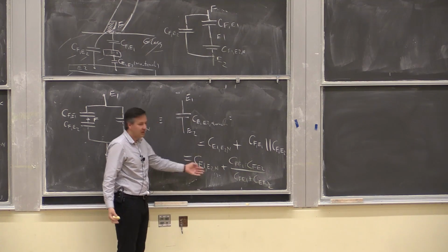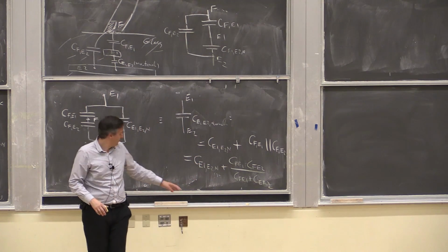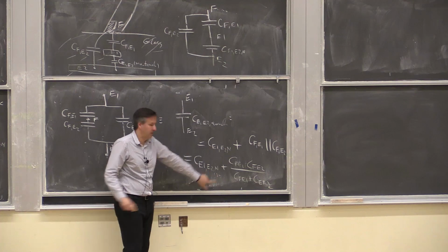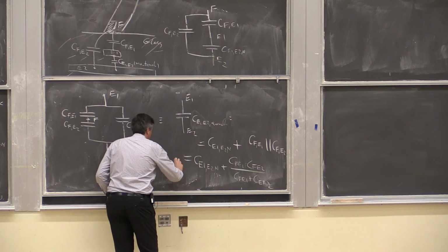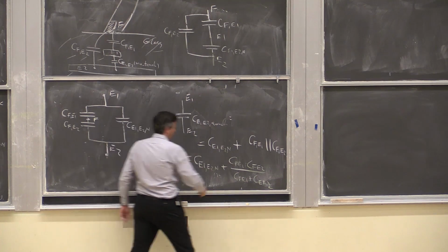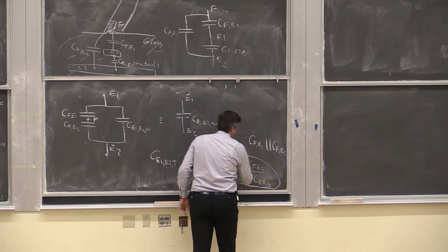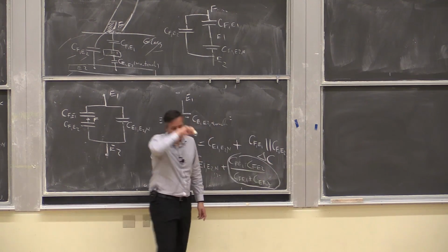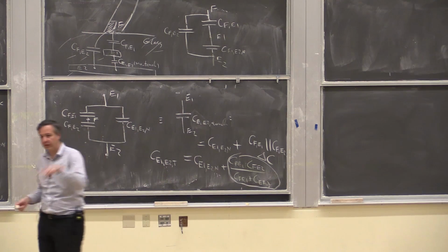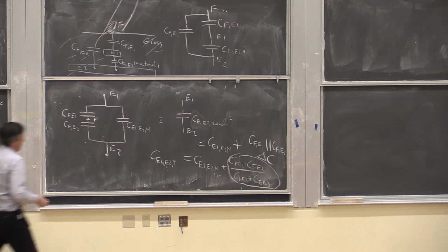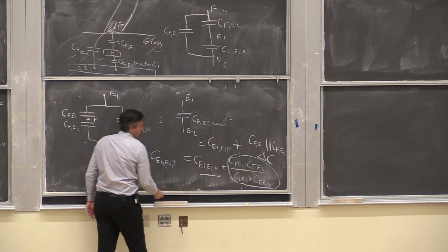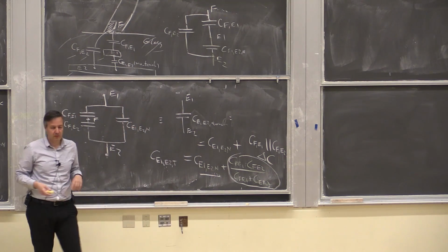Notice that this is strictly larger than just this piece, right? We're going to call this touch. So this piece over here is our delta C. That's what we're looking for. When you bring the finger close, that's the extra capacitance that gets created, and we're trying to measure that to see how much the original capacitance changed when the finger got there.